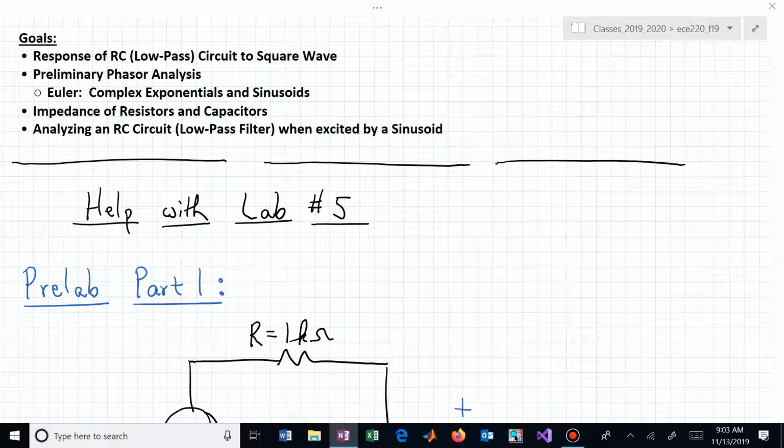What does a capacitor look like? In Chapter 9, we'll also look at what inductors look like in terms of impedance. If impedance seems a little odd, just think of frequency-dependent resistance. The resistance now varies as a function of frequency, and that's what we call impedance.